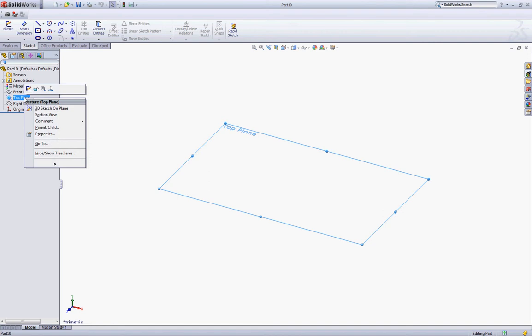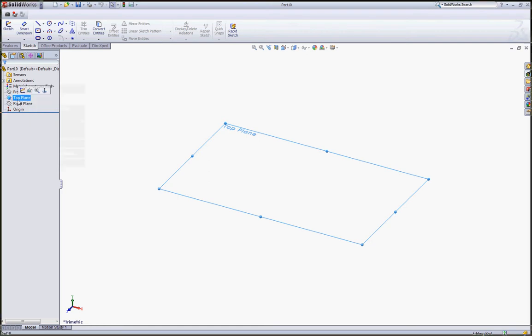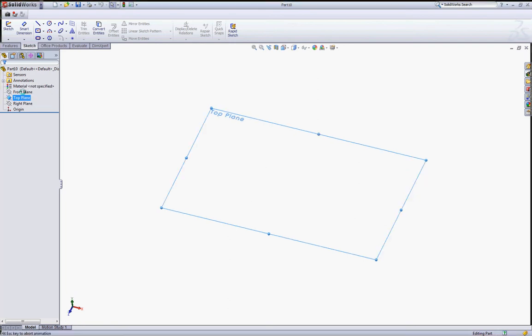So please look at the 2D sketch, because when you start your 2D sketch, you need to select one of the work planes. We have got 3 work planes: top, front, and right. It is the third angle projection. So we can choose one of the work planes to start your 2D sketch here. I will click into the top work plane and then you can see the sketch.